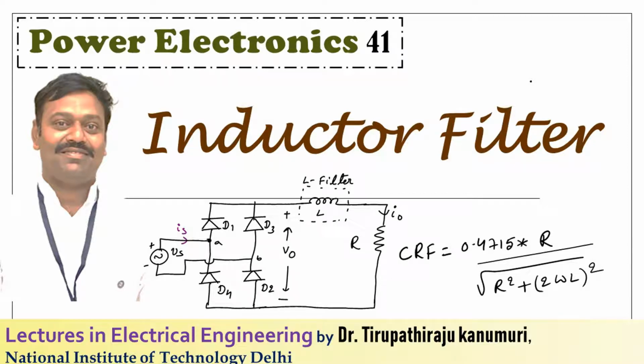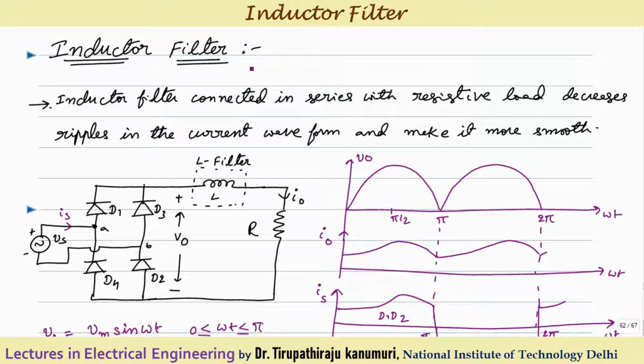Hi all, today we are going to discuss the inductor filter, and we are going to prove the complete derivation for the inductor filter, how the output current waveform becomes nearly linear, or how our output current waveform is improved. The inductor filter is connected in series with a resistive load to decrease the ripples in the current waveform and to make it more smooth.